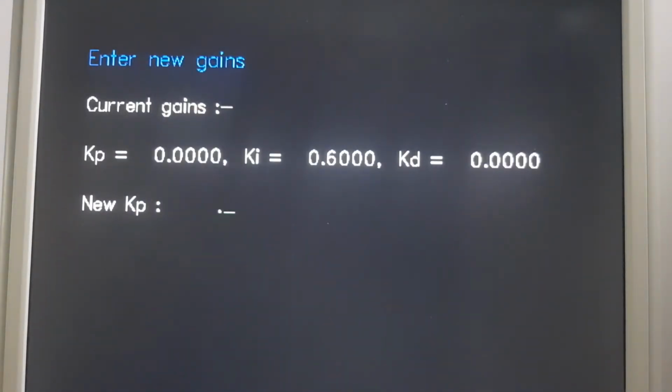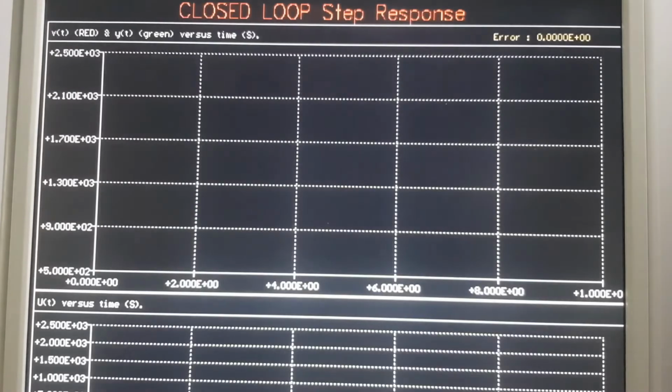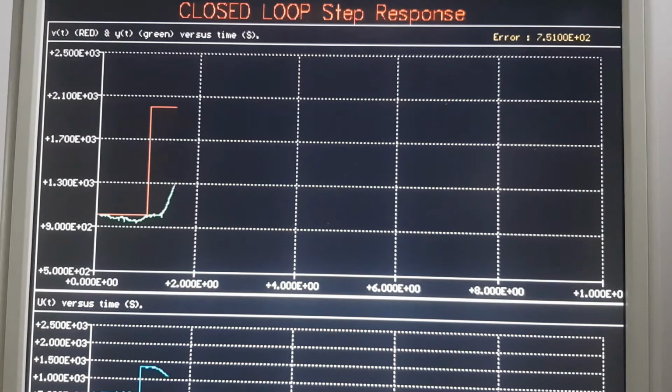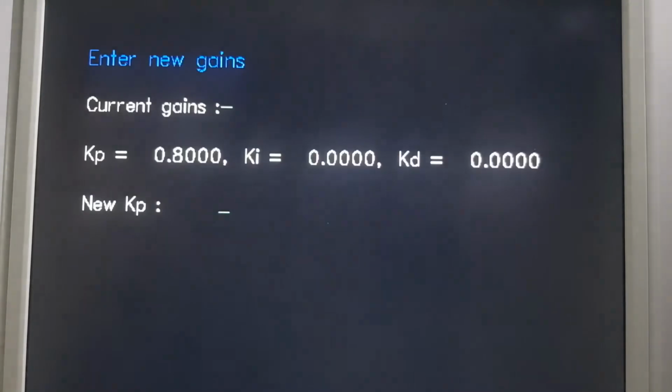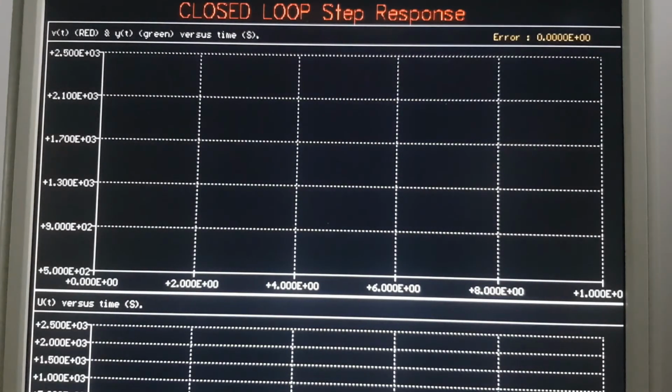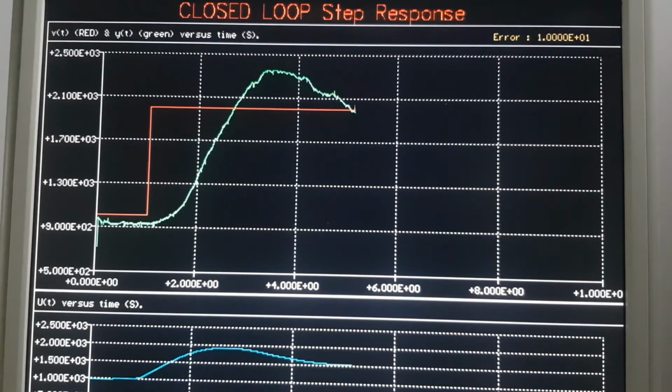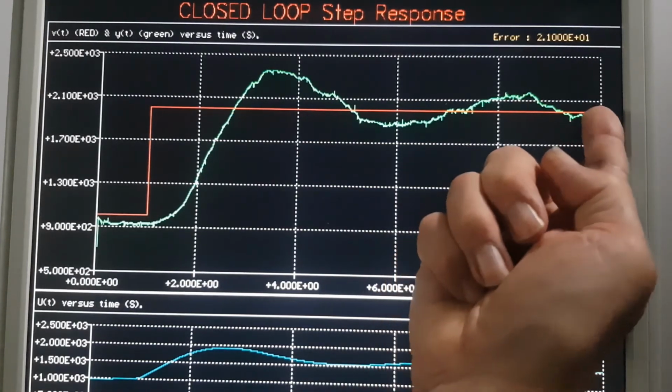So we go up to 0.8. We're increasing the integral gain and seeing what happens. This time, I've probably done something wrong there. I've put in proportional instead, so that wasn't very clever. So here we go, with the right numbers in now. This integral control with 0.8 gets even more overshoot and a little bit of undershoot, but it still has this zero steady state error. So the error down here is going to 0.